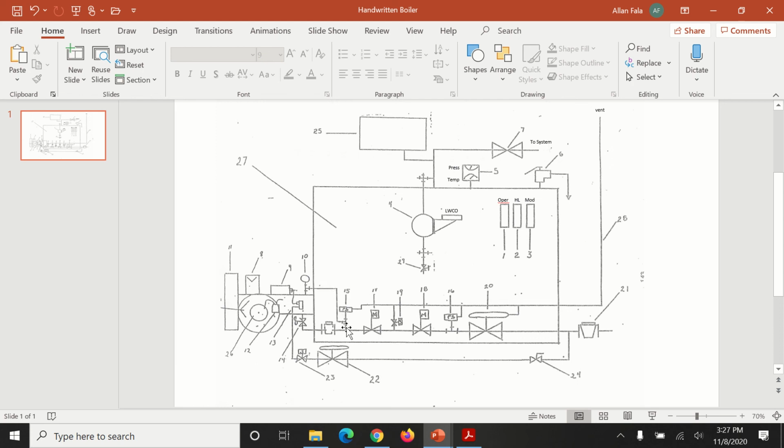So really what you'll see is that on this gas train, this nipple is welded to the gas train, but it's never been drilled, and there's no way from pressure in the main gas line here to make it to that high gas pressure switch. The pressure for that high gas pressure switch actually comes from the manifold back down here. In a lot of cases, the high gas pressure switch number 15 is actually mounted right up here with the manifold pressure gauge.